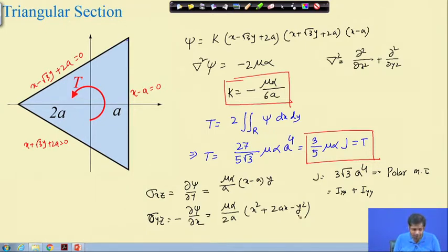See what is sigma xz on this plane. If you take on this axis, x is equal to a, this is the x axis, and this is the y axis. On this plane, the stress we have is only sigma yz. And what is the direction of sigma xz? The direction of sigma xz is in this direction, means on this surface, if you try to visualize, it is a 3D object, it is along the longitudinal direction, and that stress will be 0. The only stress we have is in this direction because of the torsion, which is consistent with this formulation.